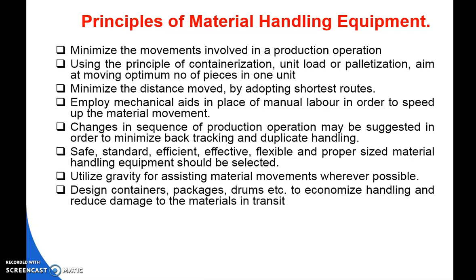You should use the gravitational effect to assist material movement, like in our crane, overhead crane, where the effect of gravity is greater. Also, we can move the materials in containers. We have to make packages, and liquids are handled using drums, to economize the handling and reduce damage to materials in movement from one department to another.